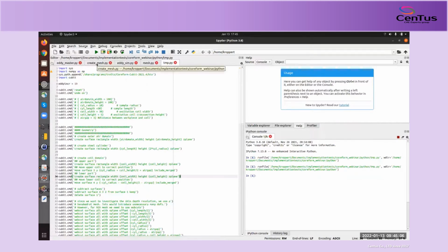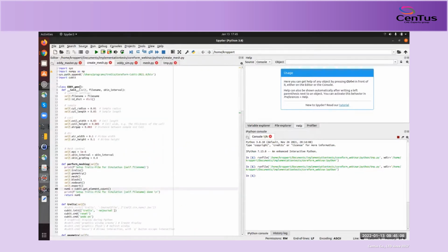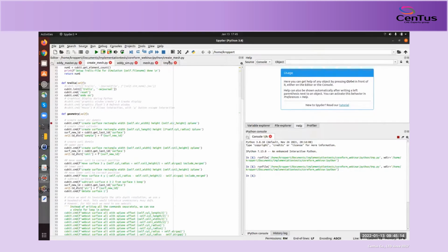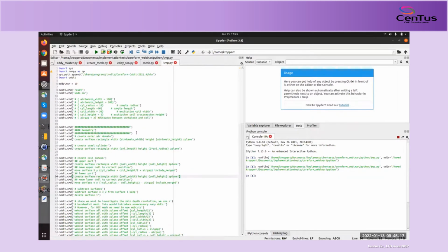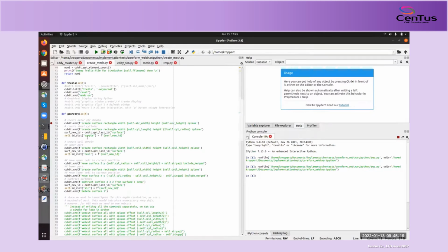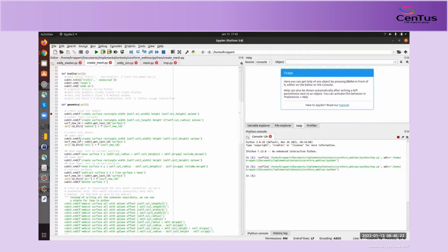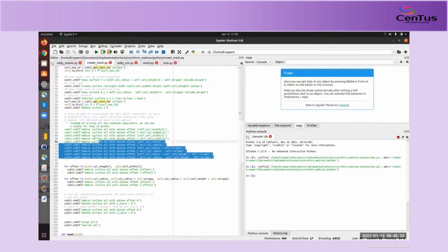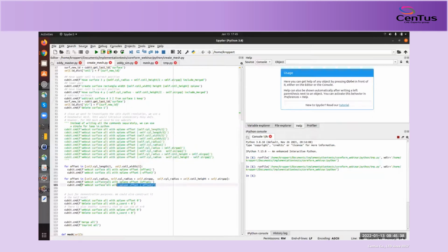For that, I've already prepared a class called eddy geometry, which is basically this Cubit file from the journal editor, but already using some Python API features. So, for example, I could get the last created ID of a surface, or another neat thing: you remember these lengthy webcut commands, we can write them down in a short way by using for loops, for example.